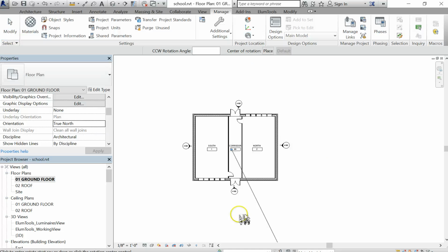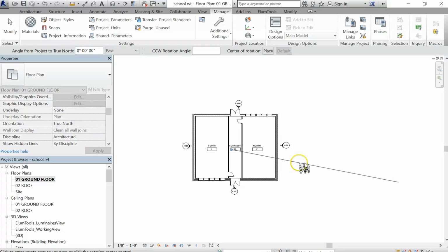And you see right away you have a rotation command. Now you might think to rotate your entire model. Don't ever do that. Just leave your model as it is. It seems counterintuitive, because what you're actually doing is rotating the rest of the universe around your little model, but it's better that way. It's better to draw your model orthogonally and rotate everyone else to you.